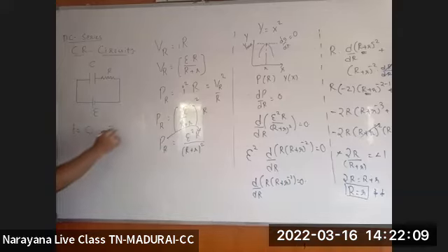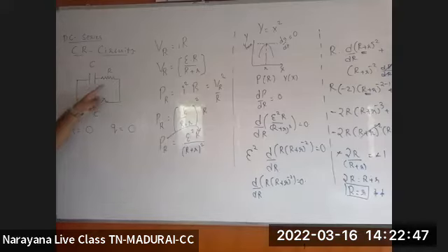If you switch it on, initially what is the charge on the capacitor? Initially, the charge on the capacitor is 0. Just now I switched on. Here one switch is there. Understood? I closed the switch, so I allowed the current to flow in the circuit. So initially, what is the current in the circuit? Think and tell. Initially, the capacitor is acting like a pure conductor, so initially a maximum amount of current passes through the resistor.